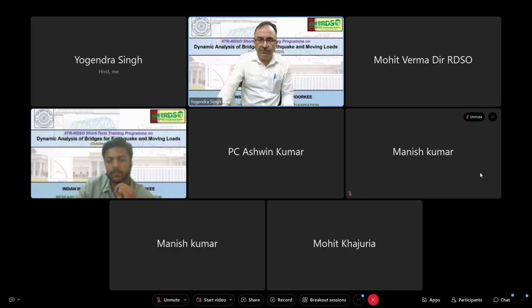So if you have taken all the modes up to 33 hertz, and you are not able to get sufficient modal mass participation, then those modes which you are not able to excite will have frequency more than 33 hertz, or the period less than 1 by 33, that is 0.03 second.